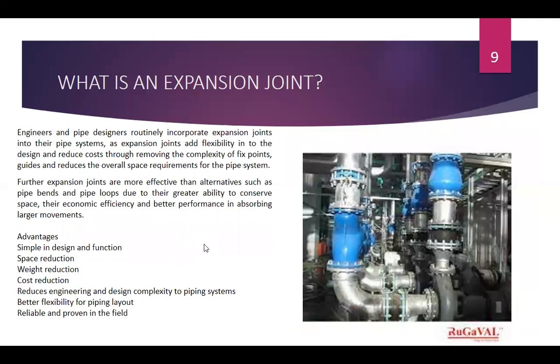So, engineers and pipe designers routinely incorporate expansion joints in the pipe system, as expansion joints add flexibility into the design and reduce cost by removing the complexity of fixed points, supports, guides, and reduce the overall space requirements for the pipe system.